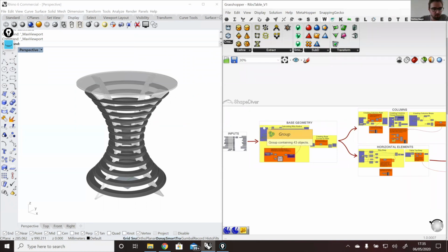And we can move on to this question that was asked a long time ago, because it was about scripting. We did it also last week. Will a definition work faster if you use Python scripting or C# scripting? In general, there are a few differences between Python and C# that are relevant. Python is interpreted on the fly, so it's always going to perform the same, whether you just open your definition or on further runs of the definition. Whereas C# scripts need to be compiled the first time they run, and then they run a bit faster because they're compiled. So in any case, Python will be more reliable over time, and C# will perform better in the long run. But the first time you send a request to the server, it's going to take a bit longer because you need to compile it.